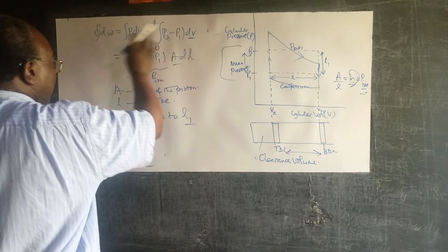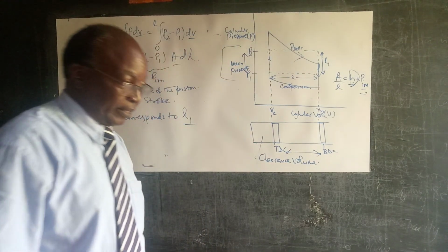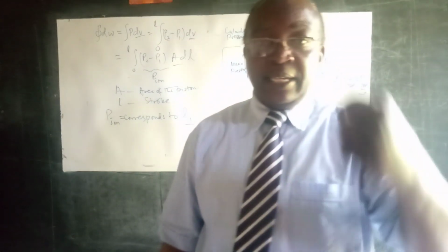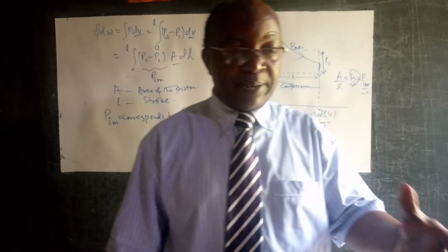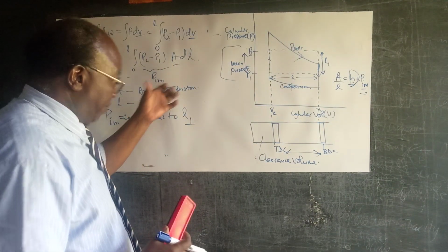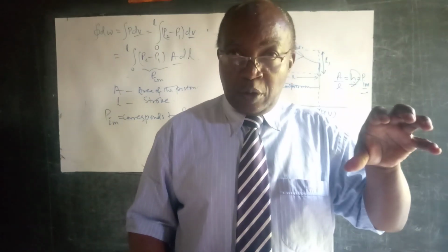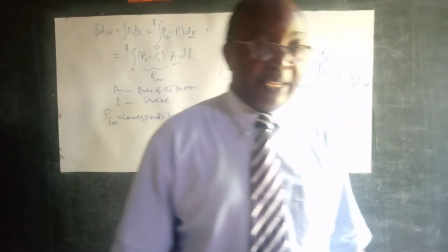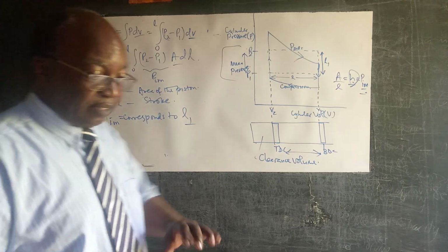So pressure times volume, like I've always said, is the work done in that particular process. So that indicated mean effective pressure corresponds to the work done by that machine. If that PIM, the effective pressure, was acting on that piston whose surface area is A, and through that distance corresponding to the stroke in that particular piston, so that's very important for us.